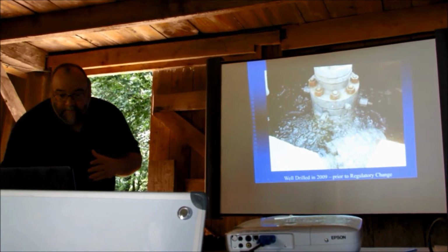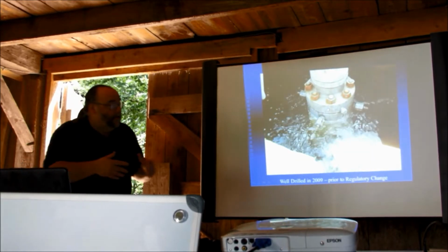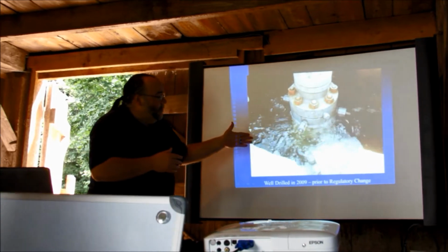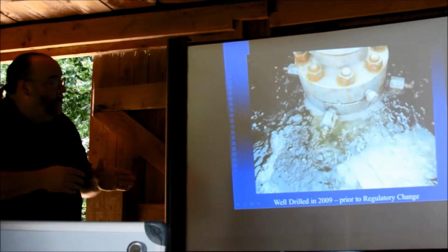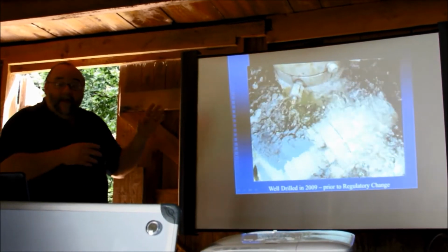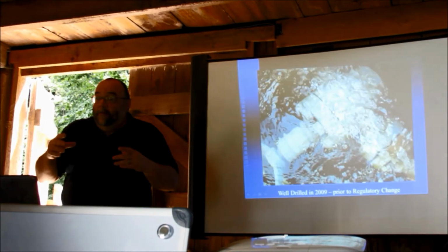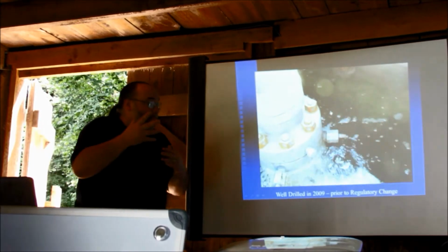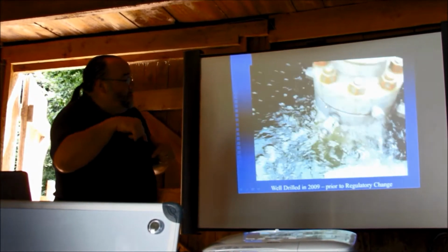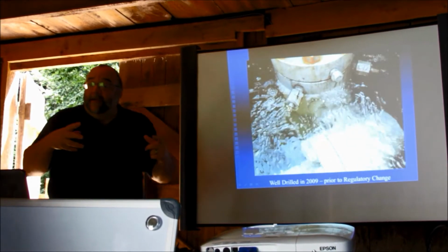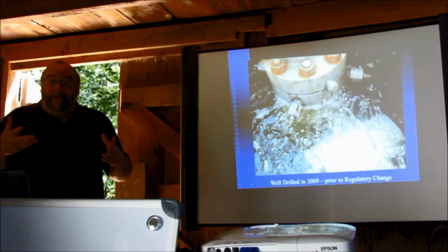This would be about 2009. This is a video of methane gas migration at the well bore itself, for a Marcellus shale well. Again, this would be a well that had that single string of pipe, with cement. The biggest issue was the use of that rather than multiple strings, especially in this area because there's shallow methane gas in the Catskill Formation that has lots of pressure.